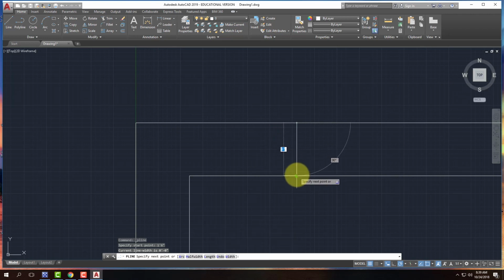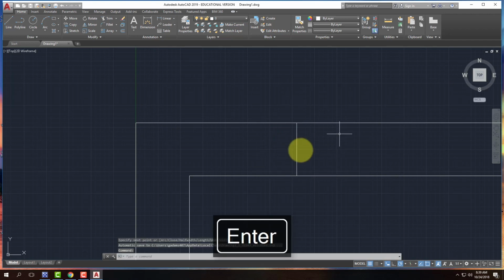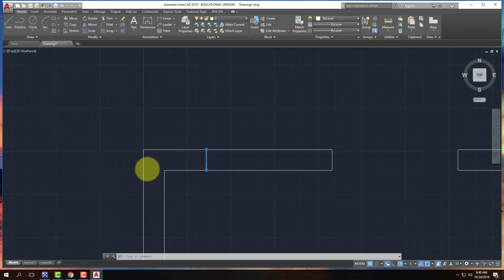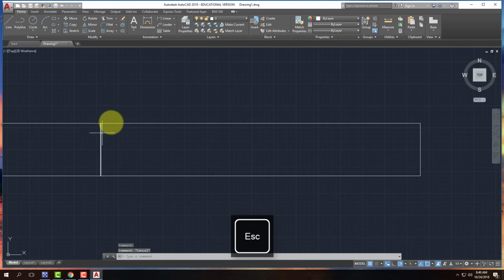So I can create this line. And the advantage here is that this line doesn't have another piece of line that's over the top that's distracting or ultimately creating double lines on my walls. So I'll do it again for the other half of this window, though I could technically just do an offset to create the other half of this window. There's always multiple ways of doing it.